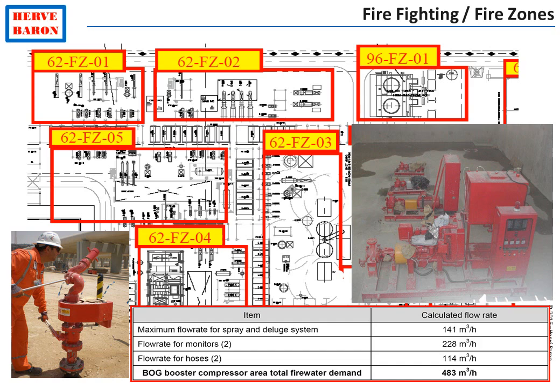Once the plant territory has been split into different fire zones, safety estimates the amount of fire water required for firefighting in each fire zone, and then takes the maximum amount among all fire zones to define the capacity of the fire water storage and pumping system.